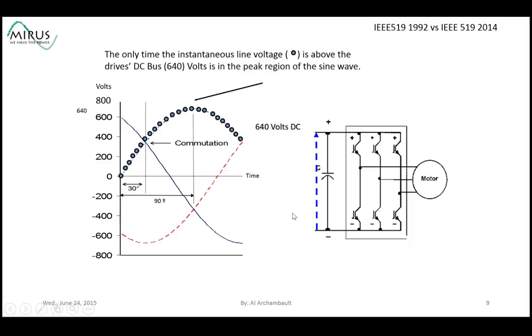Now, let's assume that we have a single-phase power supply and that the DC bus has already been charged up. Now, if I press the start button on this inverter, the motor is going to start turning and doing work and putting power out the shaft. Without the diodes connected here, this DC bus voltage is going to decrease rapidly because this is where the energy is stored to get the power out of the motor.